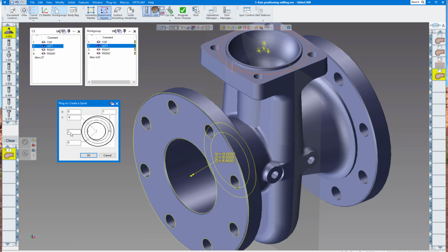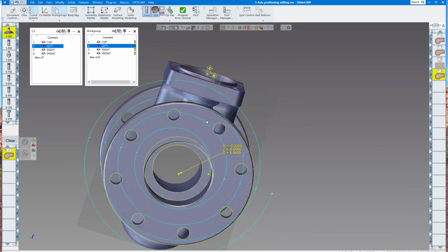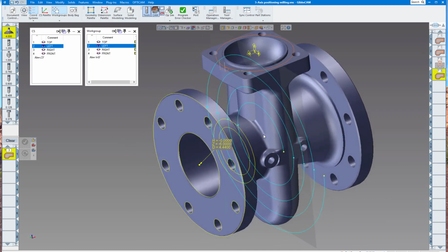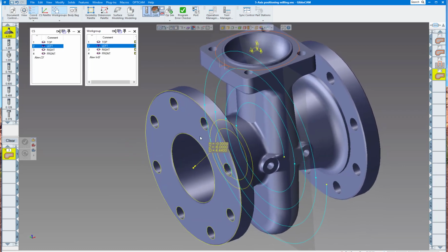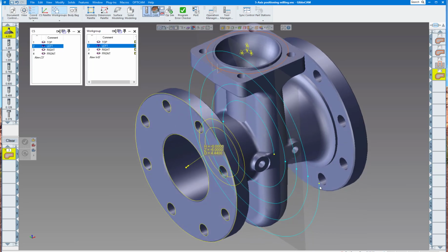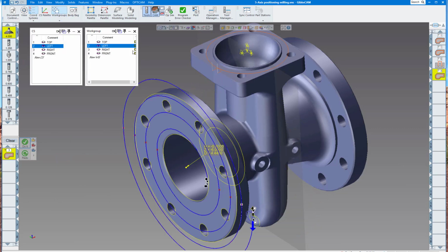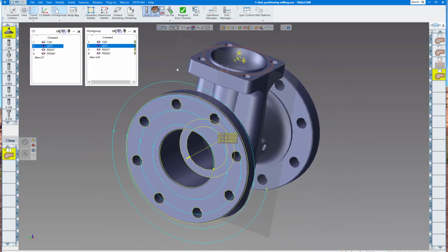We're going to start at 2-inch radius, and the cut's going to be 1 inch wide and maximum radius of 6 inches. So let's just click on do it, and you can see there's my spiral cut there. Now you can leave this here if you like, but normally I like to bring geometry up into the surface that I'm cutting. So I'm just going to select this geometry, go to modify, force the depth, alt click that face and move it to there. So now we're on this face.